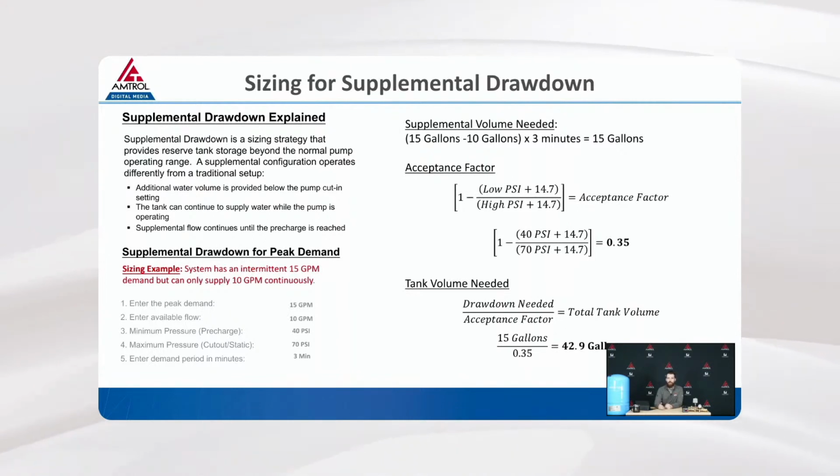As long as they have good static pressure, a hydropneumatic tank probably is the best way to go because you don't need all that extra equipment, all the electrical and all that fun stuff. It's probably a much more affordable option 9 times out of 10.